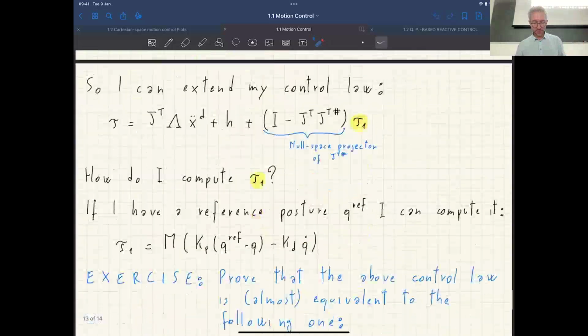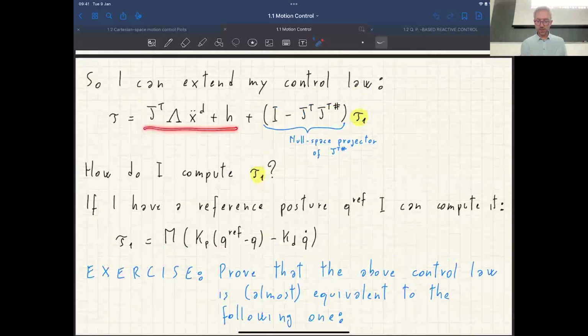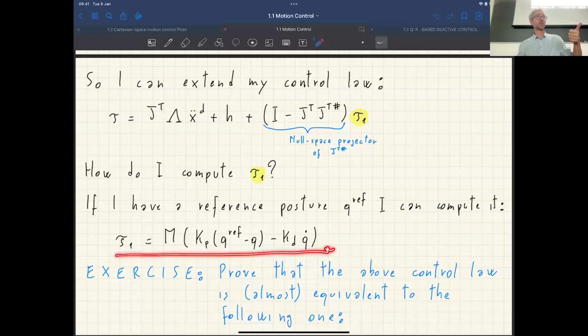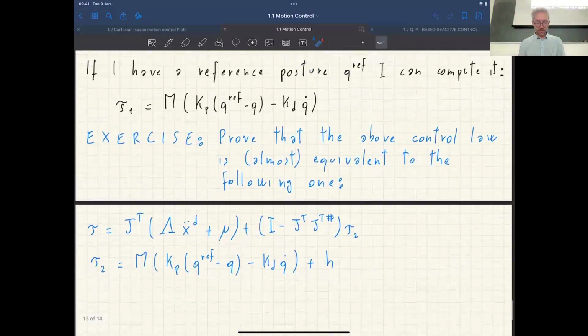And then since we have this simplified law here, I told you that in the null space task, tau1 can be defined in this way without the compensation of the bias forces, because those are already compensated for in the other term. So this is one option for writing down the complete controller, Cartesian plus joint space. And the other option was instead this one.